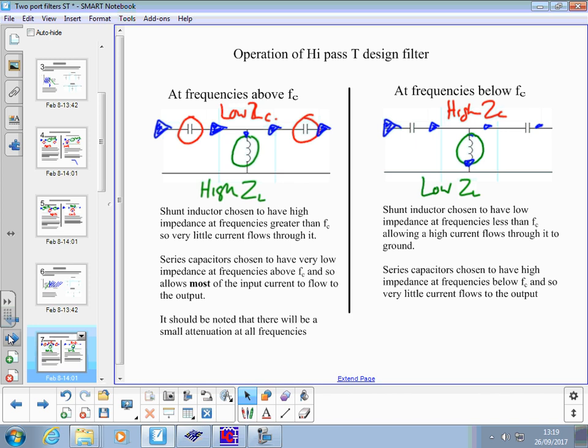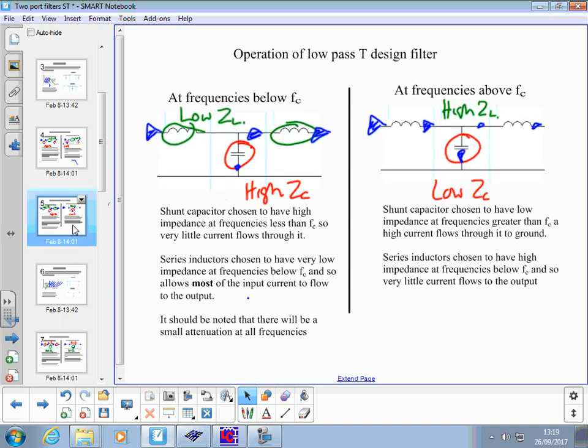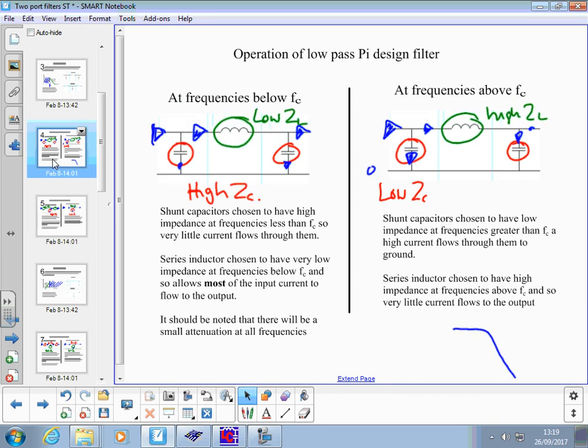Where they're in parallel in the other circuit, you'll calculate a total value for C, and then you'll put half of it in each of those two places. And that's about getting the input and output impedances to be the same value. Alright? But you can't make a filter with just one component, no.